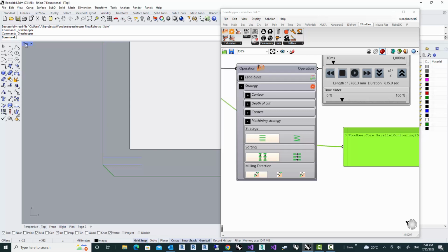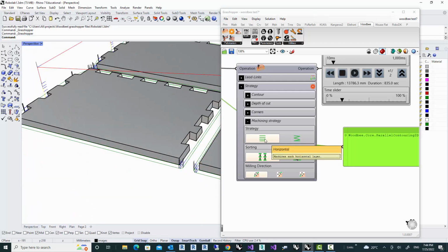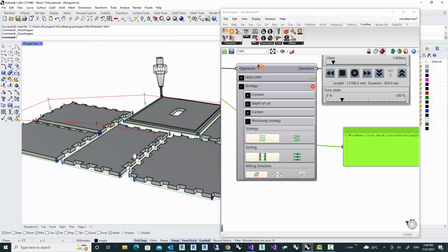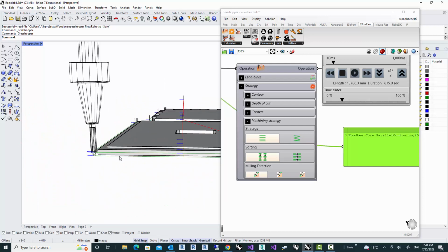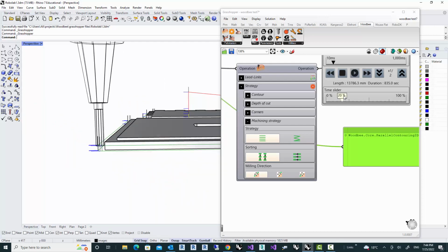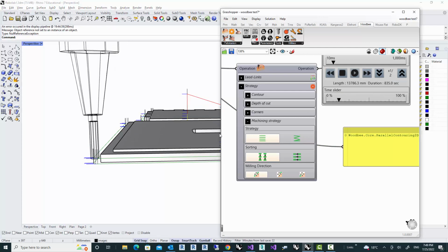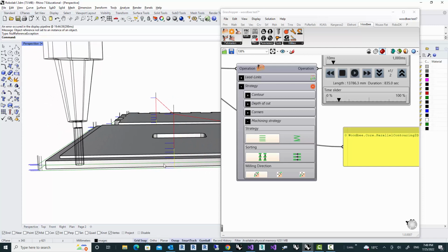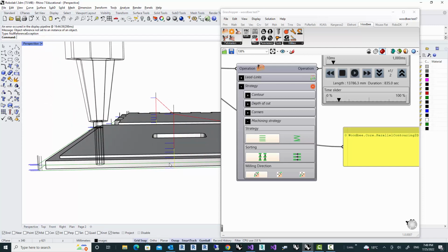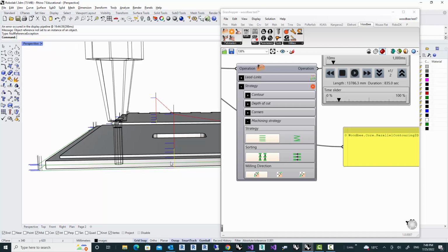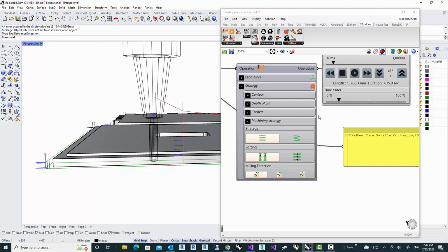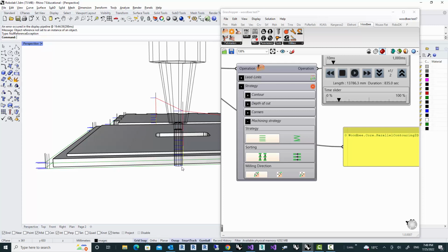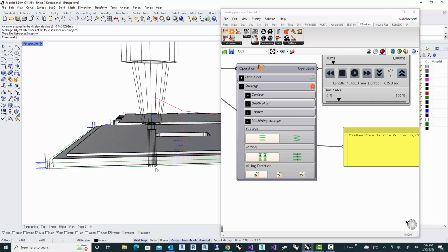The first one is called horizontal contouring. It basically means that the contour stays in the horizontal plane. So if I run the simulation now, we see that the tool is moving on the first contour, on the first level, and then when it finishes, it dives to the second level. I believe this is where the level changes because we are half through in the pad. Yeah, so now it has gone down into the next level.